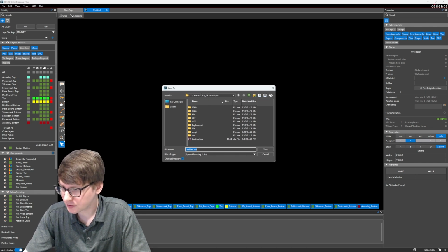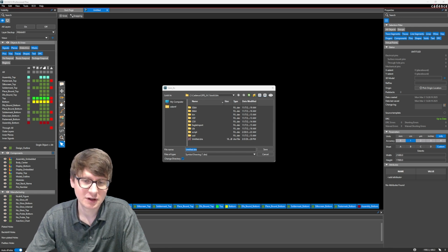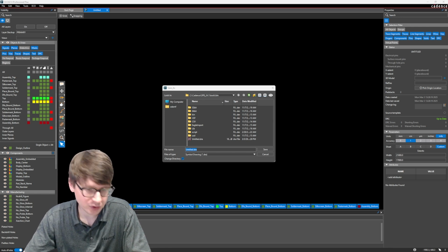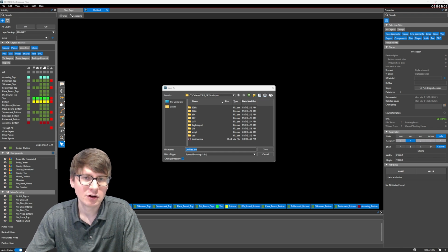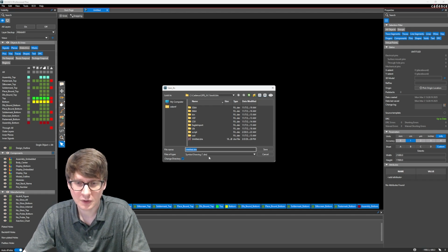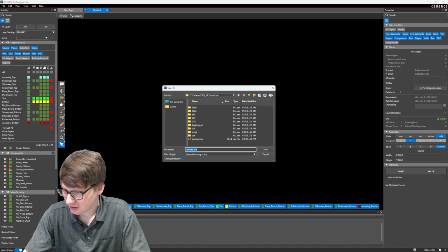Now your workspace, if you remember, is where you keep all of the required documents and symbols, footprints, etc. for the components and projects in your OrCAD X Cloud workspace. So you can see that by default, this has actually placed it in my installation directory tools bin. Not a great idea to have all of my footprints and pad stacks, etc. in there. So what I'm going to do is navigate over to my